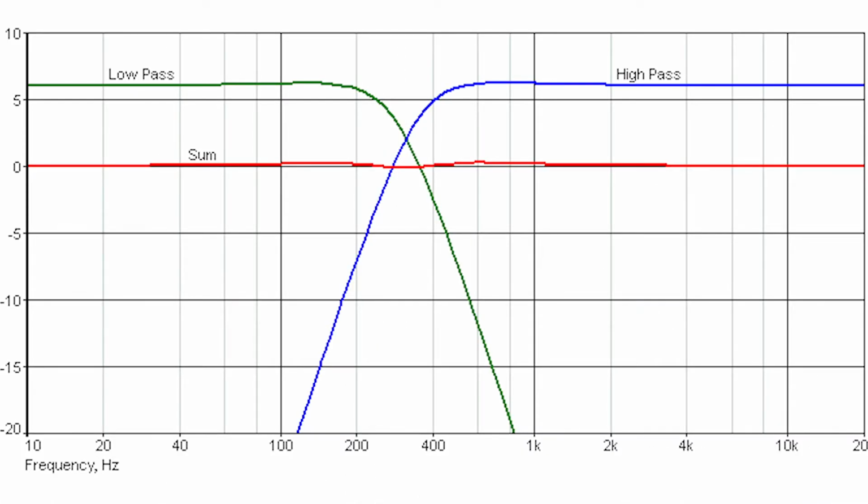The other issue with this is that with a first order low pass combined with a first order high pass, the filter slopes have a lot of overlap, which means that there will be a slight bump right around the crossover point, or a slight dip. The two sections will also have some symbiotic interplay between the overlap regions because the two circuits are interwoven.